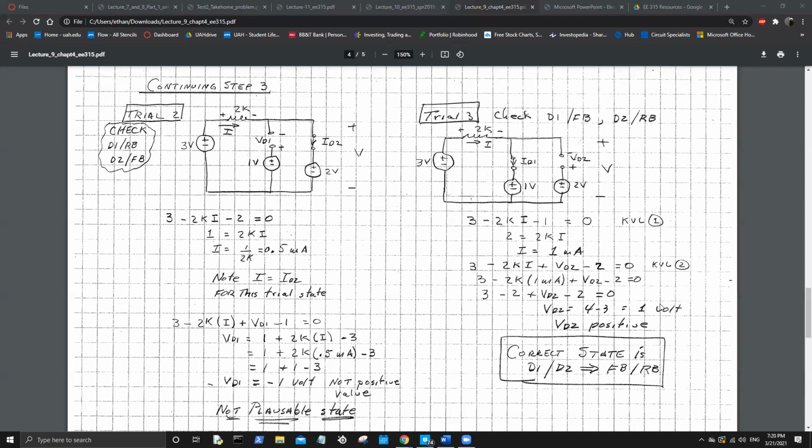All right, that's that. Are there any other topics or things you wonder? Can you think about it in terms of high and low potential voltage between the points? You could think of it that way, and you can write those potentials however you wish. I'm just thinking there's the highest potential between 3 volts and 1 volt versus 3 volts and 2 volts. So only one of those diodes is going to be on, it's going to be D1, right? D1 is forward biased for the correct state here, yeah.